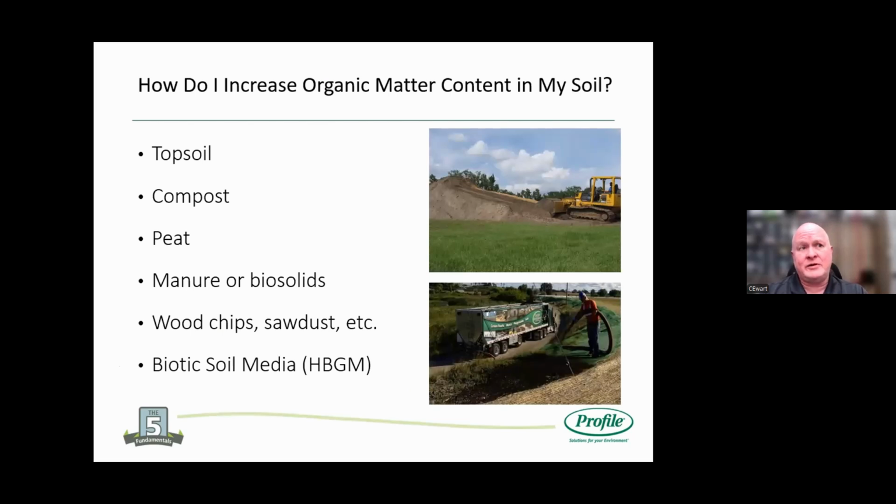So we can add topsoil. I would give a caveat with bringing topsoil in. The term topsoil is really quite a confusing term because it means lots of things to lots of different people. The thing that I'd be most concerned about is, again, if you are bringing topsoil in a project, have it tested, just like you would test the soil that's there. So if you're going to put a 6-inch cap of topsoil, test that soil. Don't assume that it's amended and assume that it's in good condition for growing. Make sure you test it.